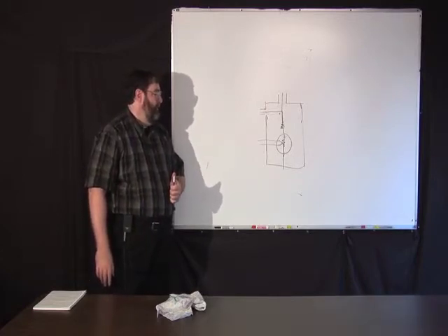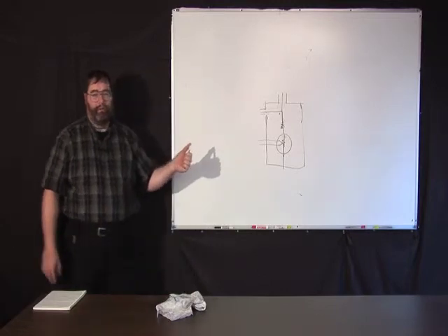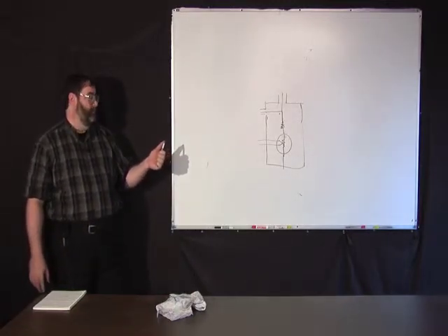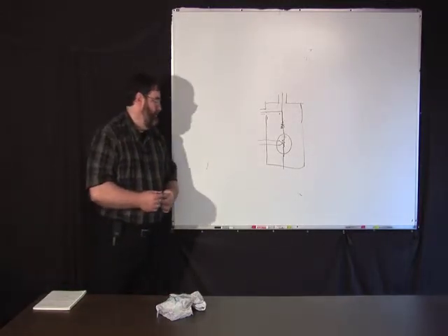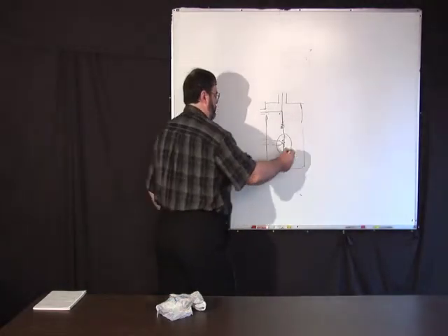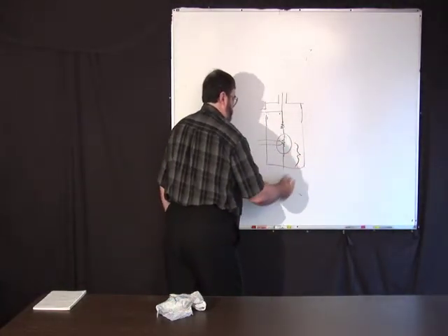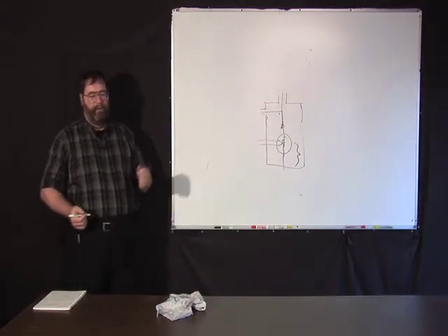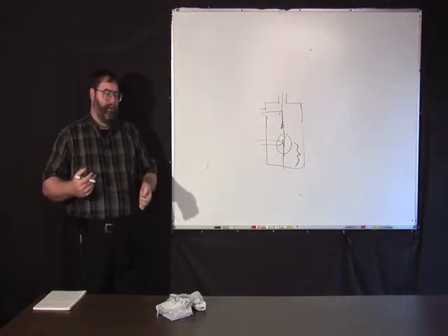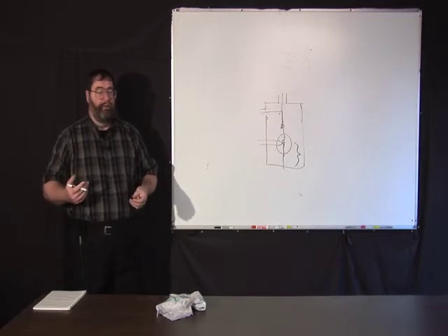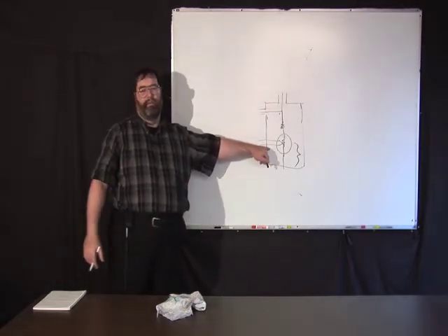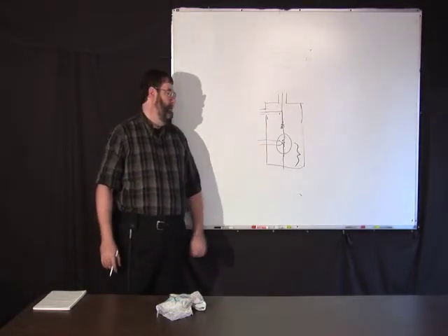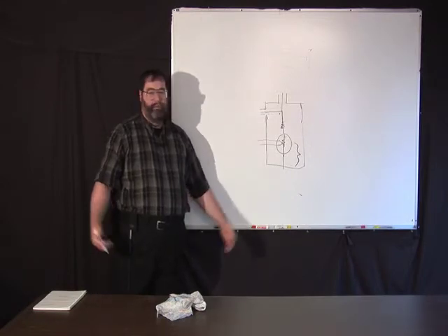Now, at some point you can't use these anymore for measuring voltage. Basically, once the distance between the edge of the container and the position of the thermal element is a quarter of a wavelength, this could conceivably be at a null in a standing wave pattern, and it would be totally useless.